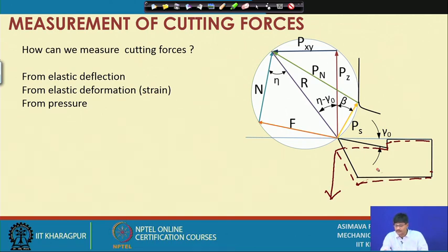If there is a cantilever beam, and if this be the neutral axis, then we can estimate the strain here to be of tensile nature, due to bending of beams, and the strain on the bottom side is going to be compressive, and at the middle in the neutral axis there is no stress at all. So we can expect something of this type to happen.